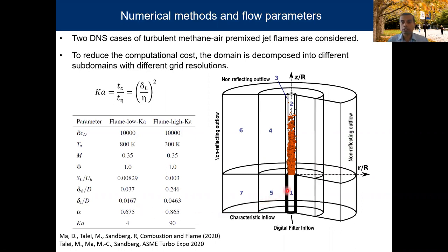So that allowed us to have a pipe flow simulation fully coupled with the flame. So we didn't have to make any assumption about the velocity field. We didn't have to have frozen turbulence here. We just had a boundary condition here, and then the turbulence was completely physical at the flame base. We simulated two different flames with different Karlovitz numbers, because these Karlovitz numbers are representative of different parts of the regime diagram.